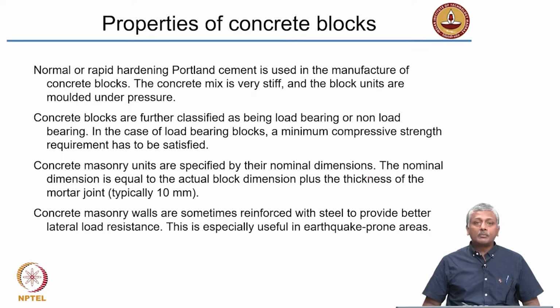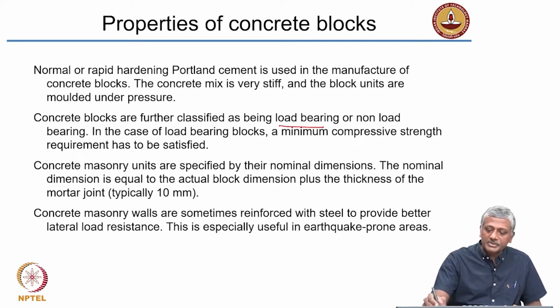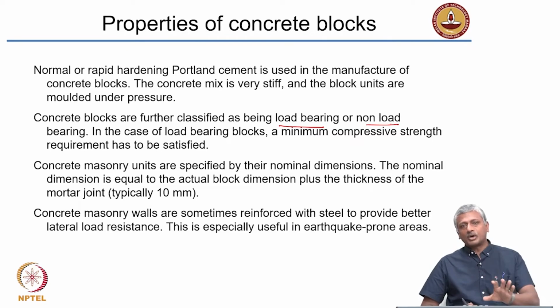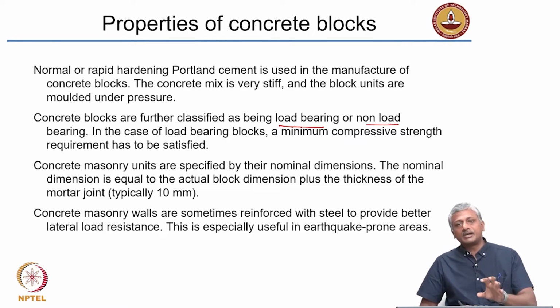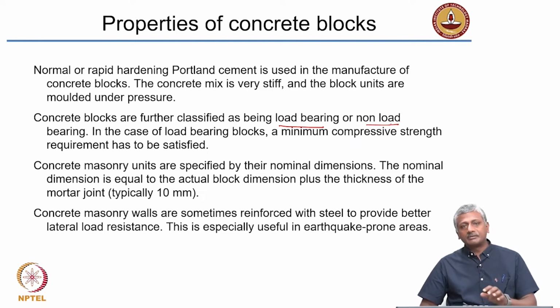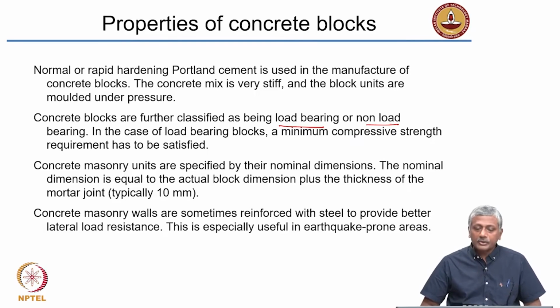Okay. So concrete blocks could be used for load bearing purposes or non-load bearing purposes. When they are used for load bearing purposes, obviously they need to satisfy a certain minimum compressive strength. I have not covered here the IS codes that deal with concrete. I have talked about stone and brick earlier, but with concrete I have not really covered the IS code for blocks here, but you can have some idea about this from reading the content in IS codes. So you need to have some minimum compressive strength to satisfy the requirement for load bearing masonry.